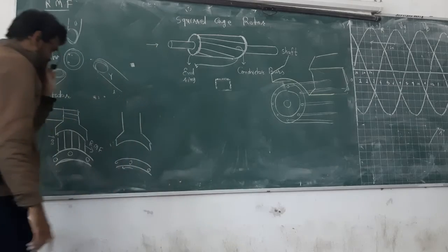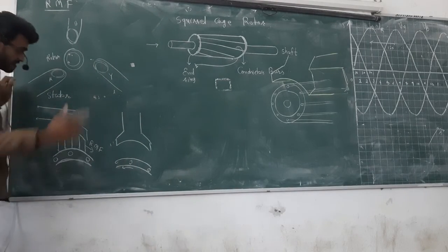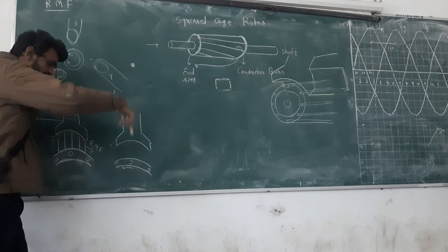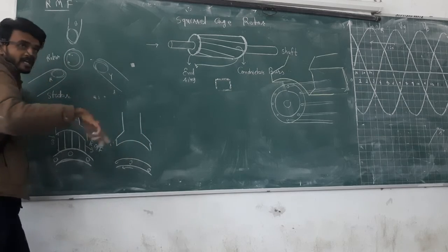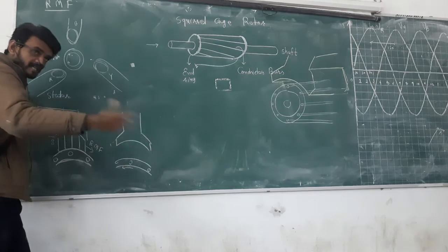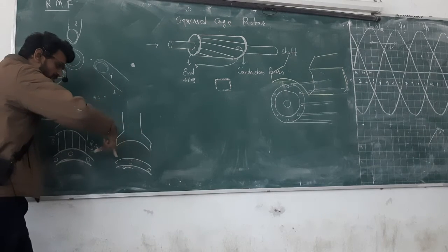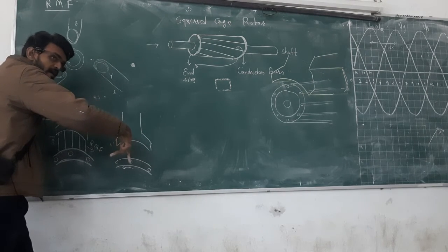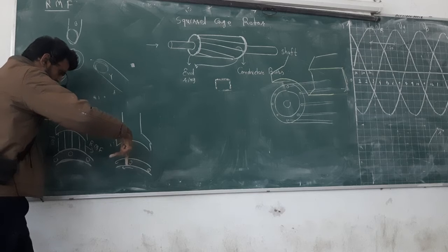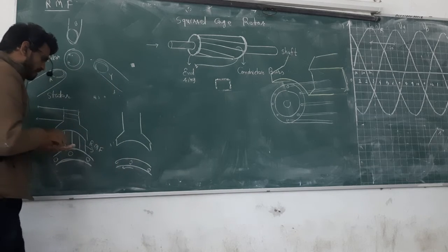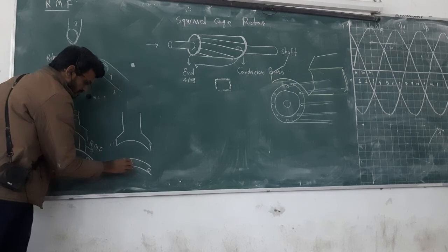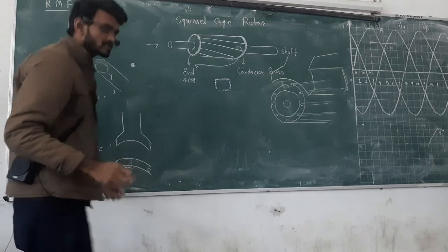And then if I apply that rule, with the magnetic field in this direction and the conductor moving in this direction, actually the conductor is not moving, but relative to the magnetic field it is moving in this direction, then my EMF, with the middle finger, comes out of the blackboard, and that is a dot coming out from the blackboard.